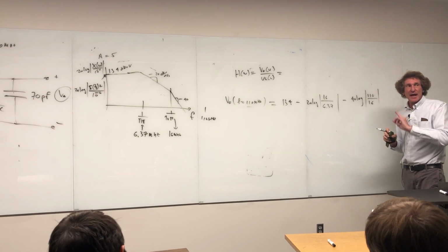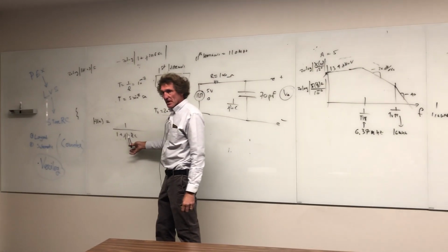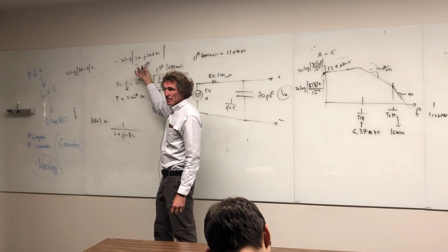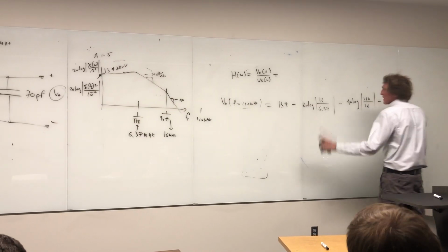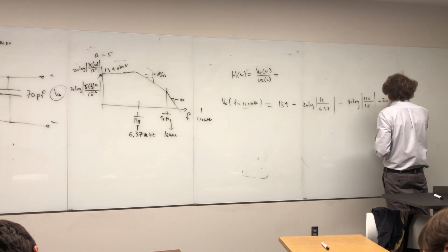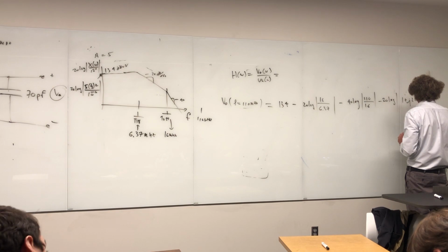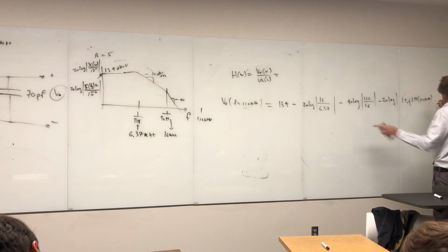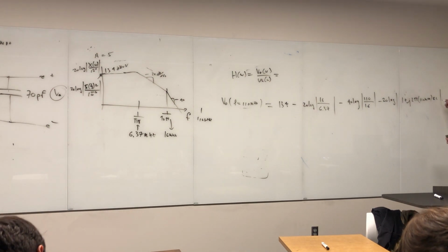But we also have to add the effect of the filter. Now the filter, remember, we had log 1 up here because it's this thing right here. So it's going to be minus the log of this at 110 megahertz, right? You can ignore that 1, I think. So it's going to be minus, and that's 20 in front of there. You all see that? Minus 20 times the log here, and then it's going to be the magnitude of 1 plus j 2 pi, the frequency, which is 110 megahertz, times R times C. Now the RC is given in the problem. R is 100 ohm and C is 70 picofarad, right?